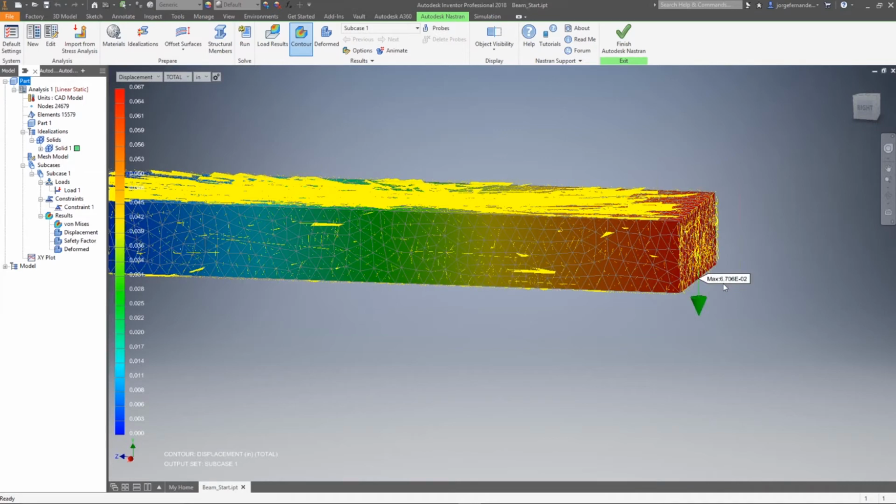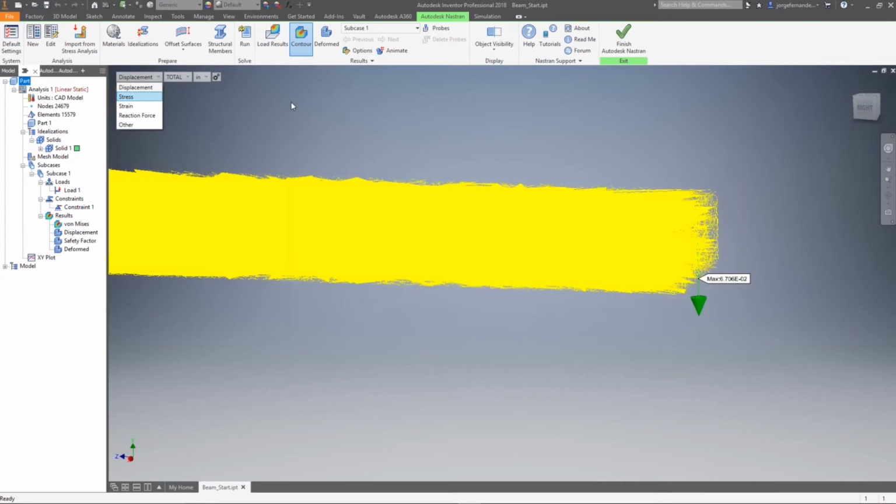Yep. So essentially what FEA is doing, if you're not familiar with the concept, is breaking this beam down into all of these little segments, calculating them individually, and then compiling them all as a result. So the more elements you have, the more refined your mesh is going to be, the more elements it's going to compile, and the more accurate your result is going to be. Obviously, you can do this to a fault. If you put infinitely many elements in there, it'll take longer to compute, right? So that's just the kind of trade-off that you have in regards to simulations.